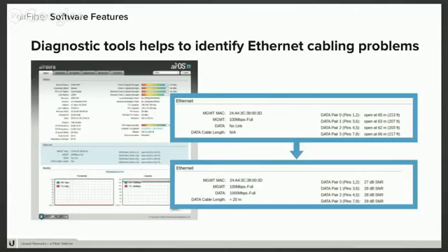If you look at the top blue square, we have a link that is running, and it's actually an RF link. But on the far side, we've disconnected the data pair. So you have a cable running from the radio down to the power injector, so it's got power. But then the cable coming from the power injector has just been disconnected. This shows you very quickly, on the right-hand side, that all four of the data pairs show an open at about 200 feet. So you're looking at about a 200-foot cable down to a PoE, which has then been disconnected.